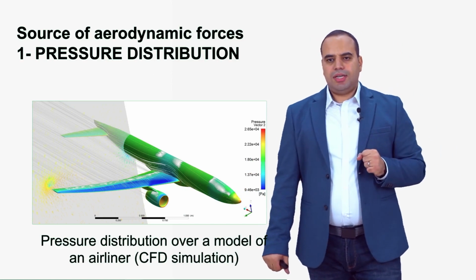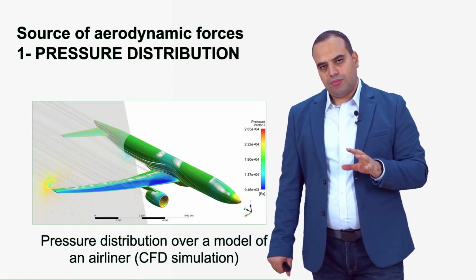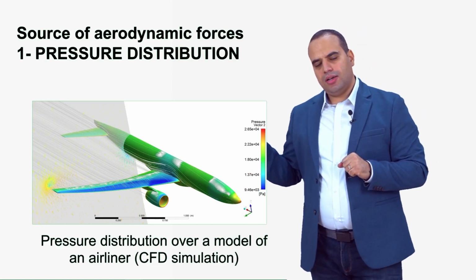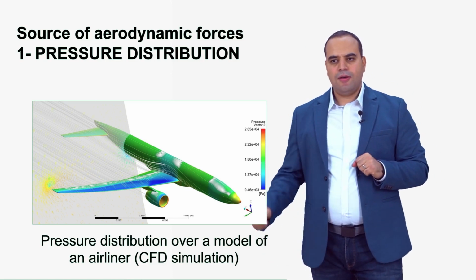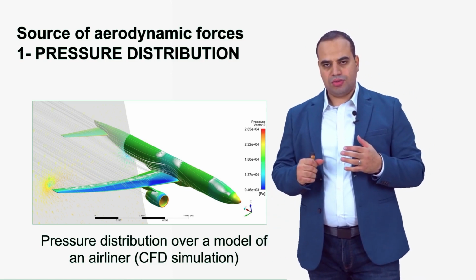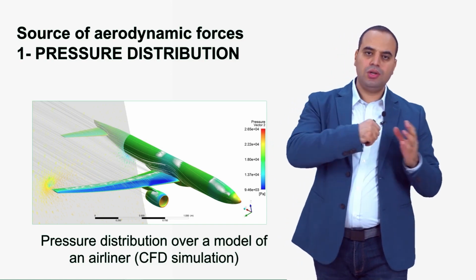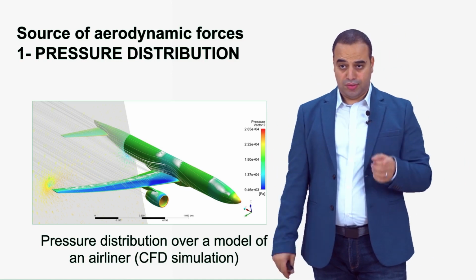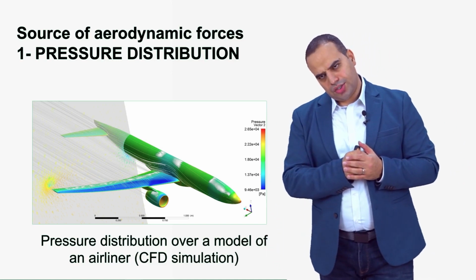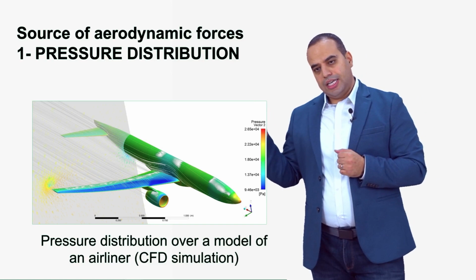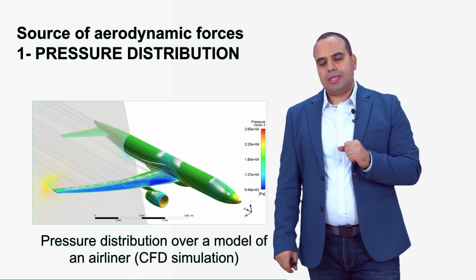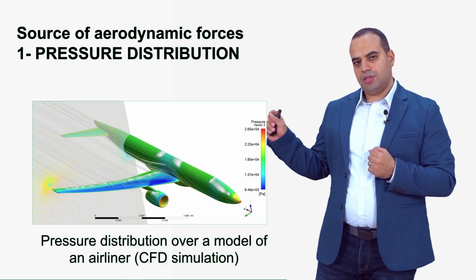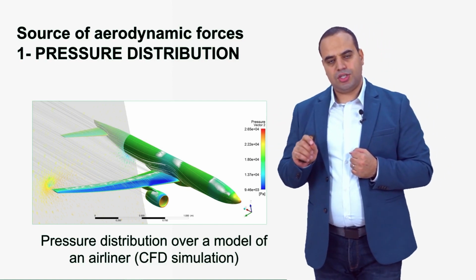Now this is the three-dimensional picture, and here we can also see the regions of low pressure above the wing. We can see that the nose of the fuselage is red, for instance, which means there is a high drag there, because the fuselage is attacking the gas, and therefore the particles accumulate just at the nose, preventing its motion forward and generating drag. Also, the leading edge of the engine nacelle is red, which means drag too. And the top surface of the wing is blue, which means very low pressure, which means a very large amount of lift is generated there, right?